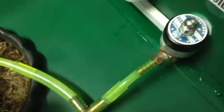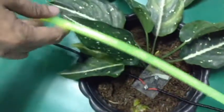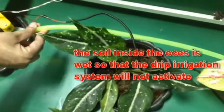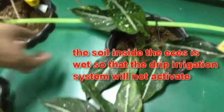For the irrigation system, the default soil moisture limit is 450 moisture and the current soil moisture inside the greenhouse is 309 moisture, that means the soil inside the greenhouse is wet so the drip irrigation system will not activate. If the soil moisture surpasses the default soil moisture limit of 450, that means the soil inside the greenhouse is dry and the drip irrigation will turn on.